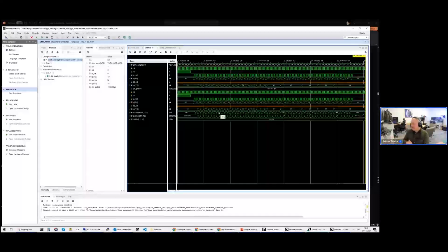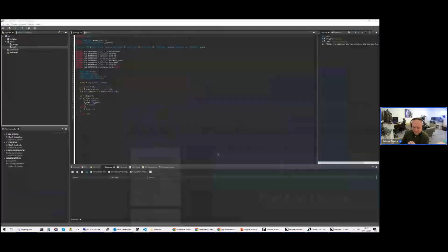There's not an equivalent of doing this in Verilog or SystemVerilog that I'm familiar with, but typically I do more VHDL than Verilog, so maybe there is, and if anybody knows better, please comment, because I'd be interested to know. You can run that through in the simulator. I'm not going to spend a lot of time on it. Yes, Vivado does support 2008 synthesis, all these example synthesis, but you've got a test bench that you can take a look at, and you can work through an experiment with.